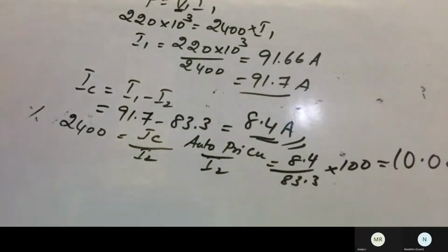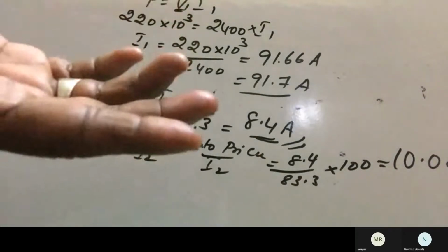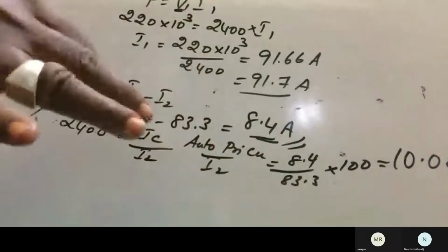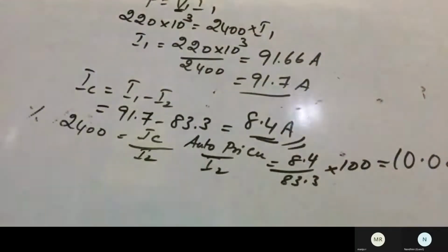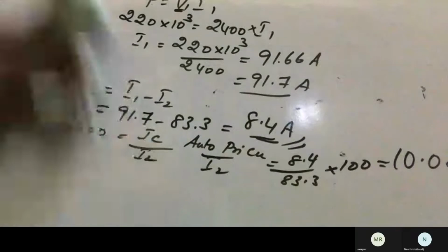Okay, the single winding will be taken for the primary as well as the secondary winding. So in the previous case, we had taken a double winding, which has been converted into a single winding, meaning the primary winding gets overloaded by this much percentage compared to the two winding. Okay, so now we can see about the parallel connection of two winding transformers.